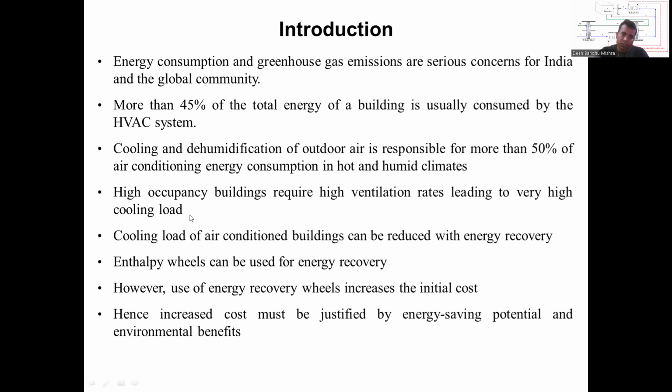To avoid these challenges and reduce the cooling load of the cooling coil, an energy recovery based cooling system may become a solution. Among all the energy recovery wheels, the enthalpy wheel is one of the best solutions because in an enthalpy wheel there is interaction of sensible and latent load between the supply outdoor air and the regeneration exhaust air. And the problem of overcooling of air can be avoided with the application of a desiccant wheel.